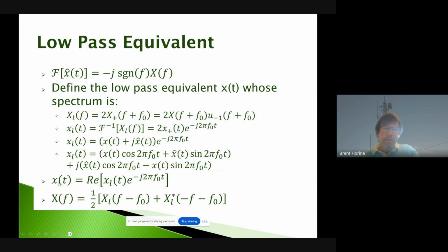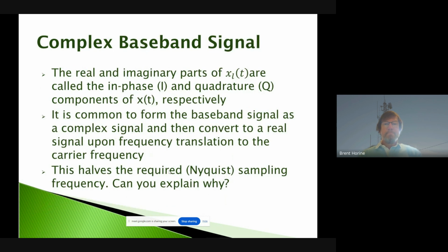And we can look at the frequency spectrum of this and note that, yes, we're back to a Hermitian type of relationship. And it's now a bandpass centered around this F0, the central frequency. We use different terms for it, but it's usually designated as an F sub 0, right? So, all right, the complex baseband signal is what we'll work with.